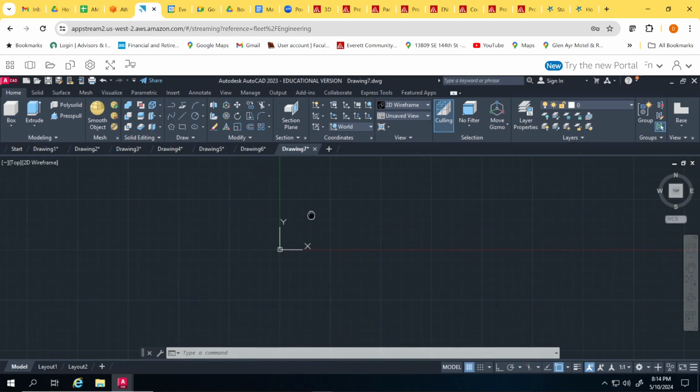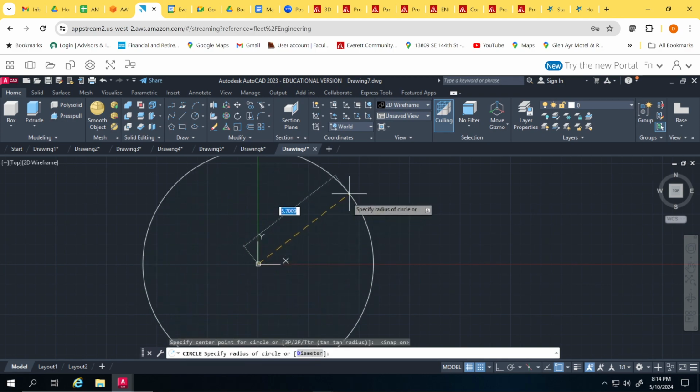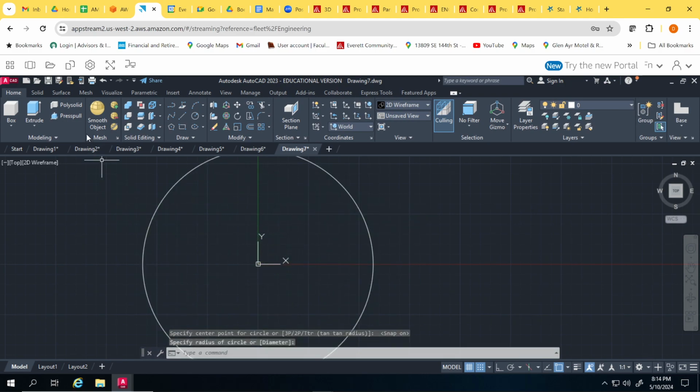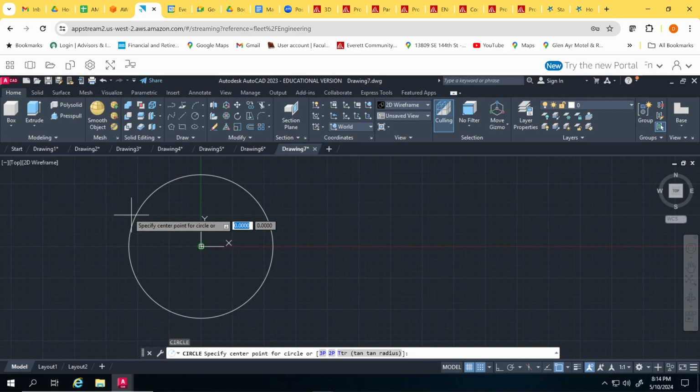To make life real simple, we will create a circle right here on that grid. So I'm going to use my snap to grid. With this on, it can snap right to the 0, 0. I want to make sure my next circle is on the same center, so I don't have to reselect that. You can hit the enter button and it remembers the last feature and the last parameters.